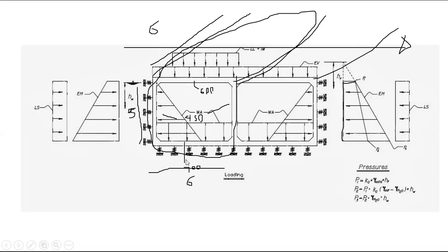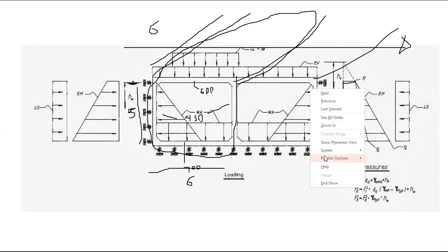And you will have spring supports for this one, because unlike if you model it with a pin support, a pin doesn't allow you to settle or translate. So it's not actually the realistic behavior, because the soil settles when the load is applied.